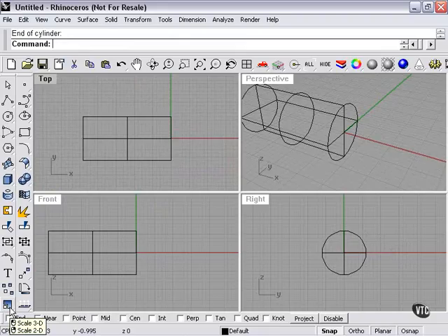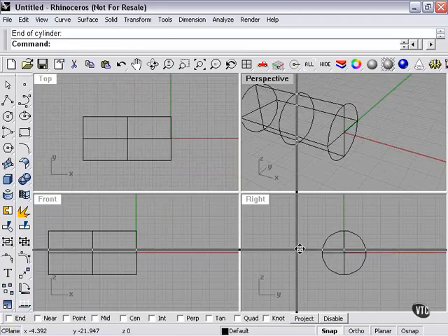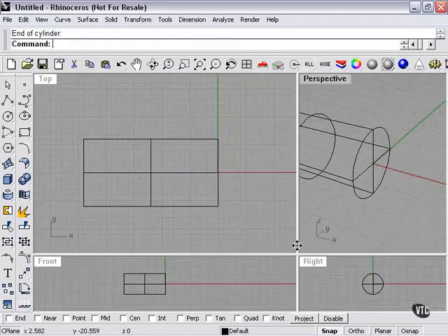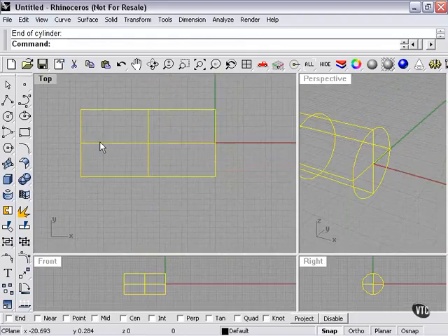As you can see, it's Scale 3D and Scale 2D. Now, by the diagram, this shows that if I left-click, I'm scaling 3D. If I right-click, I'm scaling in 2 dimensions. I'm going to make my top window a little larger by dragging on the center of my viewports. Okay, we'll select our cylinder, left click.